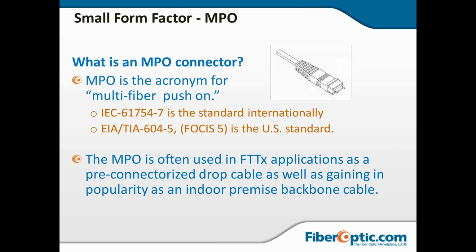No splicing in the field is necessary. Now, the multi-fiber push-on is covered by a couple of standards. The IEC 61754-7 is the international standard, and the EIA-TIA 604-5 or FOCIS 5 is the U.S. standard.